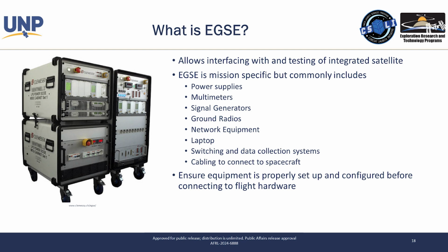while it's being integrated. This is another thing that's often left too late, where if you say, well, I got a radio and I'm pretty sure it's going to emit at 915 megahertz, and so I'm good. Incorrect. We'll get to the tests in a minute where you actually need to prove that.